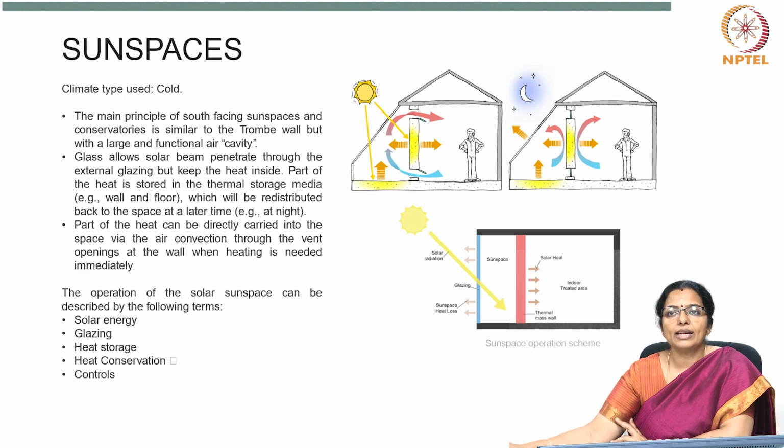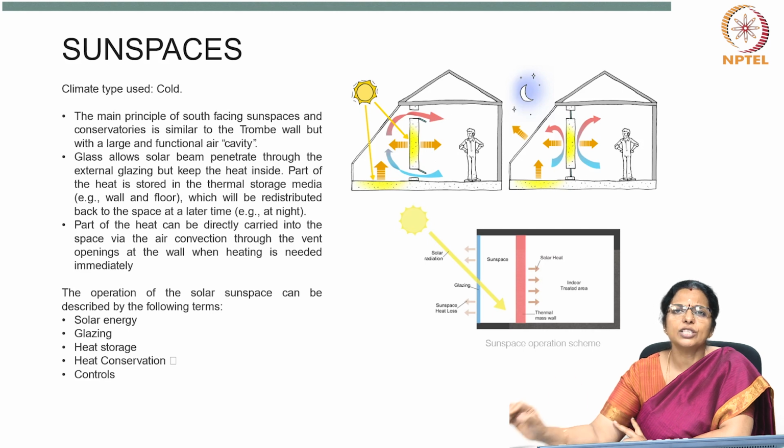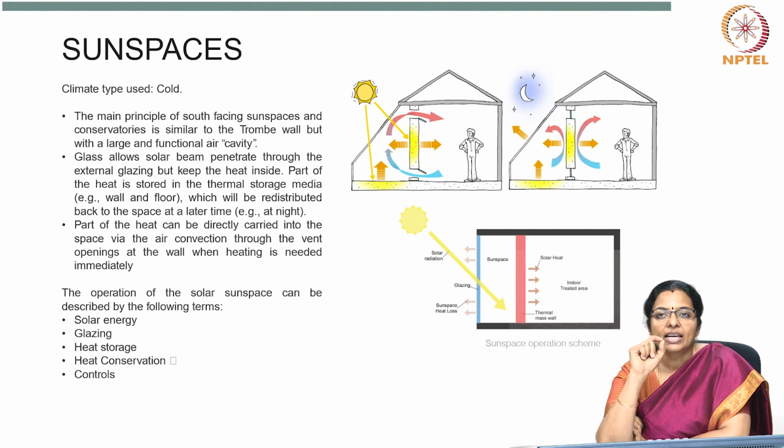So, these two main parameters can affect the reflectance and absorption, and that has to do with the material and the angle of incidence. Multiple glazing could also be used, and the use of more than one layer helps in reducing the heat losses, as the gap between the layers, which is usually air, acts like insulation.